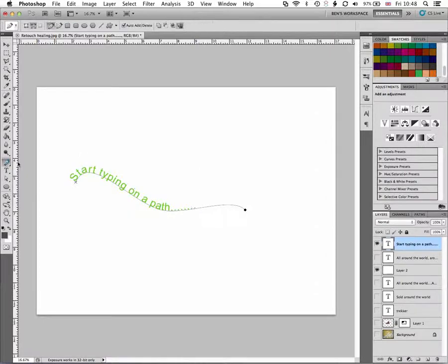The key thing here is just how the circle and the shape tools are easy to use, but the pen tool is a little more tricky to play with. So when you first start using it, you may find that you have to switch your head into pen tool mode to actually get it looking nice. It's actually hard to get perfect paths. I tend to use shape tools and combinations of shape tools to actually get a real nice path.